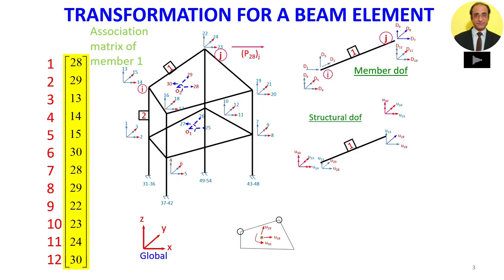However, we need to do transformation of the stiffness matrix of the member before we can transfer the elements. Now this transformation has to take into account the rigid body diaphragm action of the floor slab, because in our present formulations we are considering the displacements, the floor degrees of freedom, at the reference point. Similarly, the member end forces also need to be transformed to this particular point.